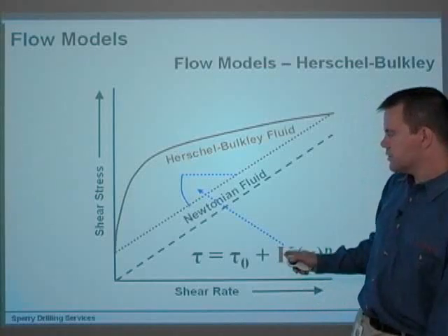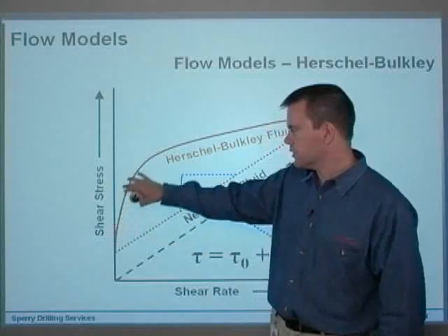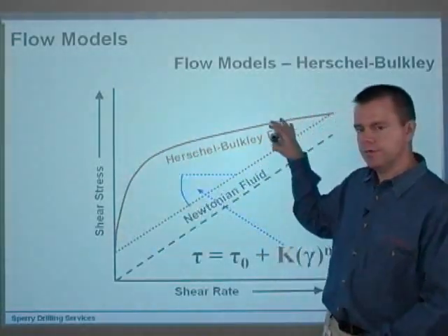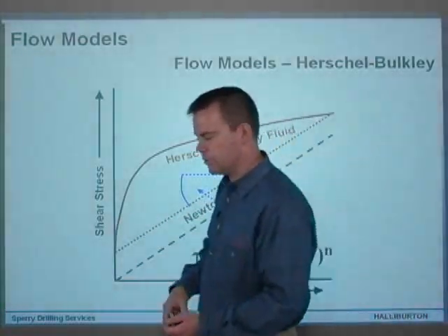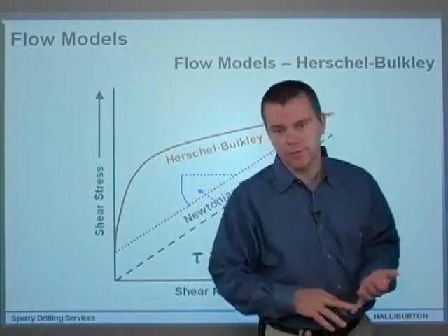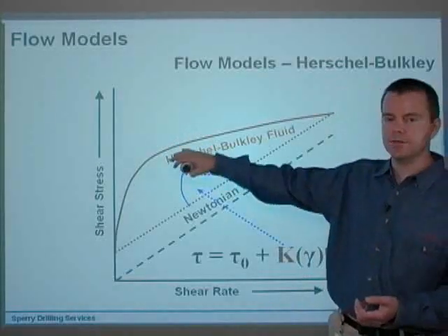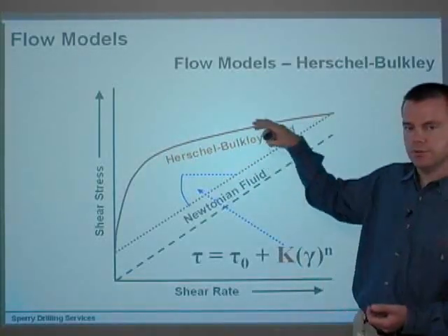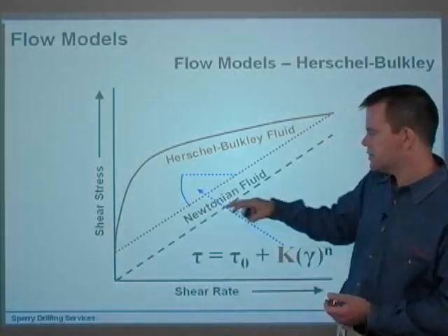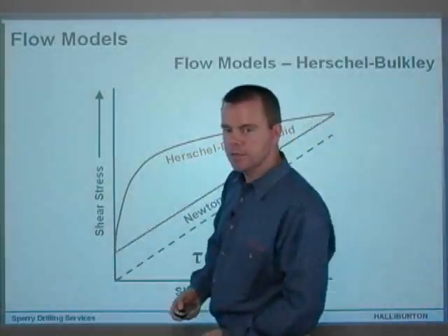Now k in this is actually describing the slope of the line. n and k change throughout the model, because you're using a variety of different values. That's one of the beauties of this model. You actually input 6 rheological values, and it will change n and k, producing a curve for the annulus and up through into the pipe flow regime as well, the flow area as well. But k, put simply, determines the slope of the line.